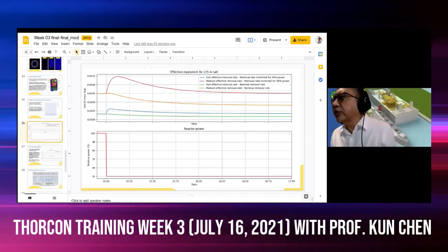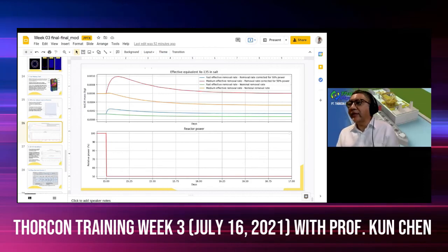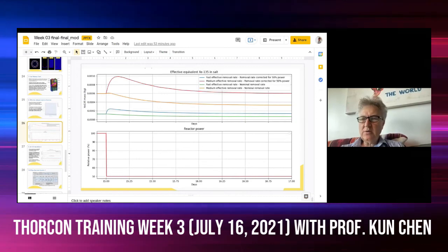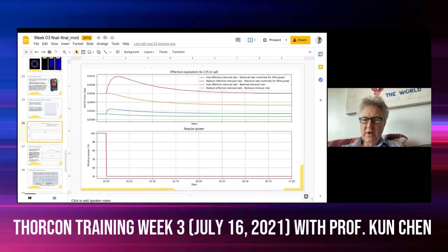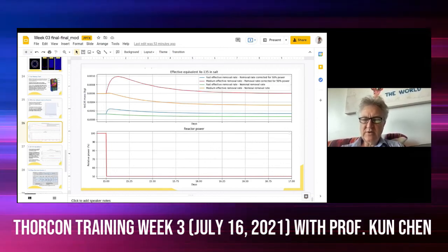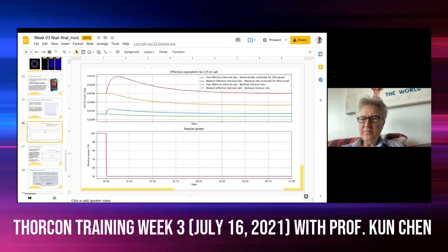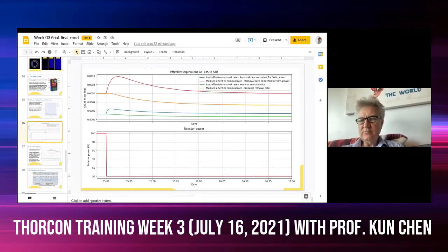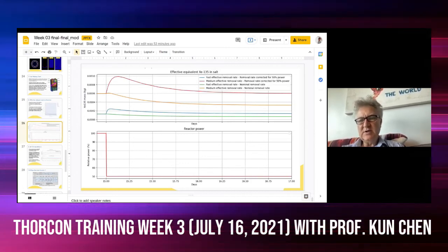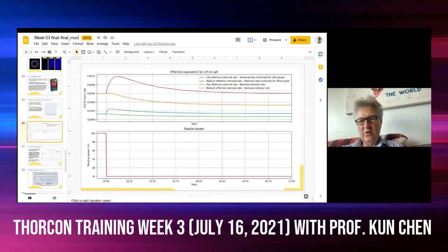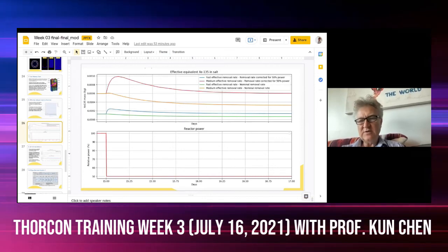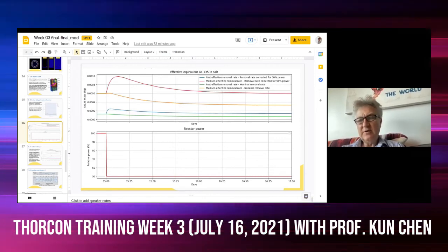And about the control rod shutdown margin, I think that hasn't been answered, Lars. So the control rods, we are targeting to have around 2,000 pcm on 3 control rods when they're all inserted, between 2,000 and 3,000 pcm. So that's your margin. Remember, this reactor doesn't have burnable poisons, and it doesn't use the control rods for trim. So the worth of the shutdown rods themselves is the margin we have.